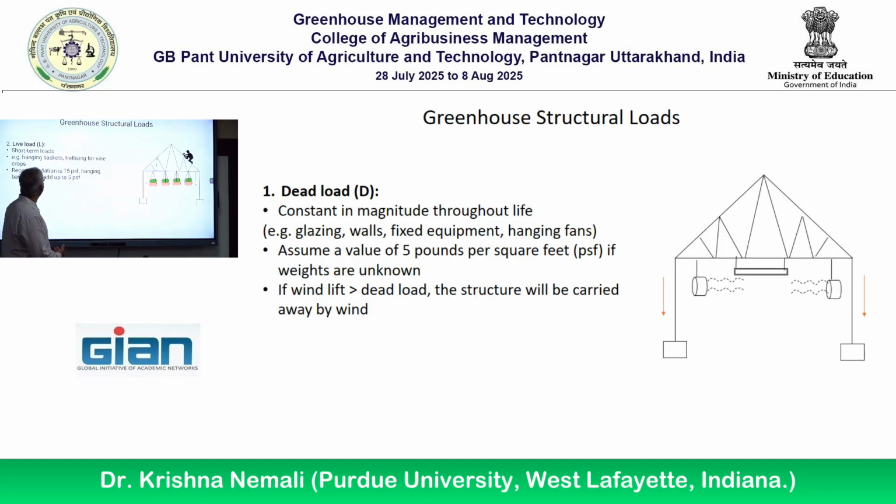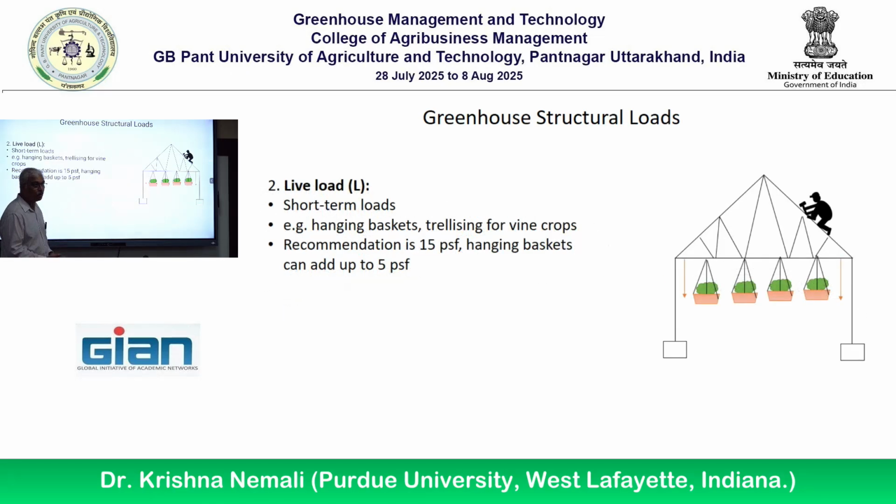All right, the next one is called live load. Opposite to dead load is live load, right? I'm giving you some examples. What is this guy? He's up at the top of the greenhouse. He's doing repair, right? He's standing on the greenhouse. He's putting his weight onto the greenhouse, right? What we call point weight. At one point, he's putting weight. He's probably 80 kilograms, 100 kilograms, who knows, in weight. But he's adding that weight, isn't it? So your structure should also be able to hold his weight when they stand on that.